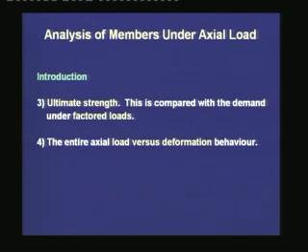Third, we shall study the ultimate strength. This is compared with the demand under the factored loads. That means in a limit state design, we compare the ultimate strength with the demand under ultimate loads, which is the factored loads times the characteristic loads. And finally, we shall study the entire axial load versus deformation behavior to understand the full property of the prestressed concrete member.